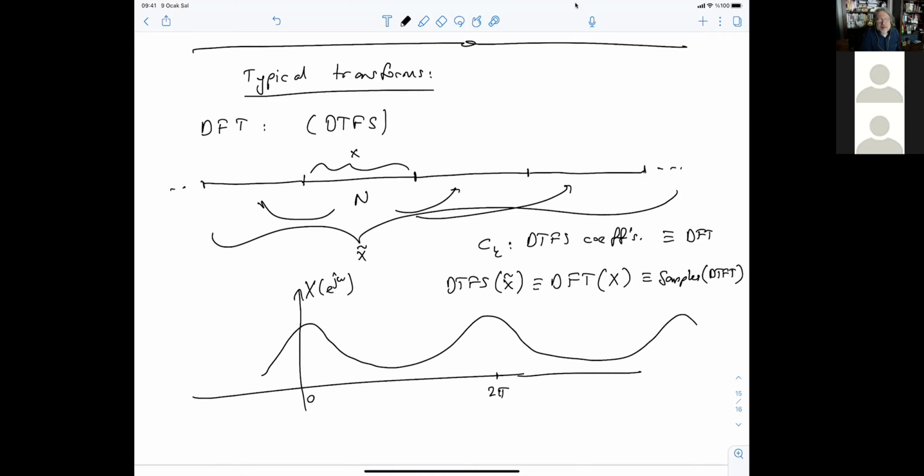You may remember from signals and systems. So DFT at N points, depending on the number of elements in this vector, will be the samples of this. For example, if it is 2-point DFT, then the sample will be this one and the one at 0, which is this one.